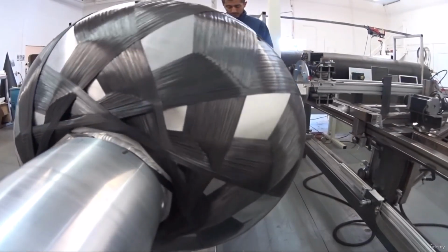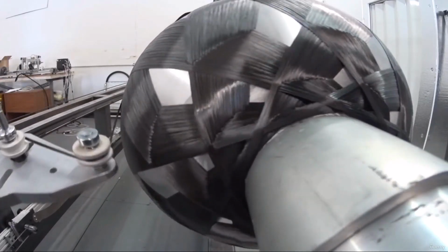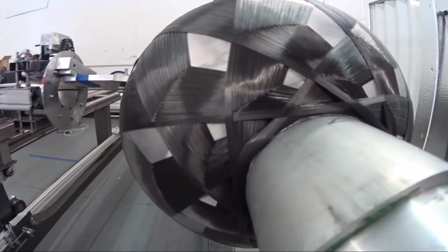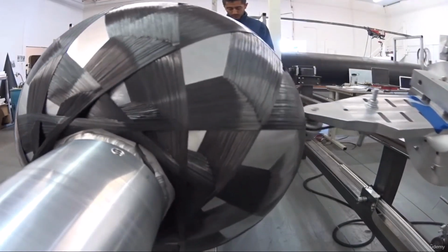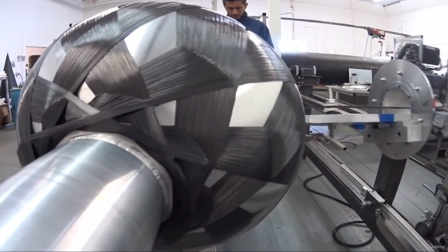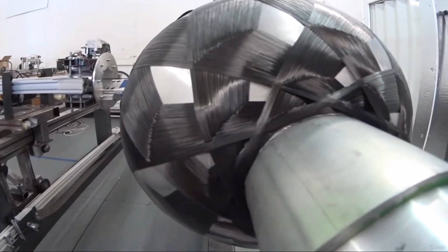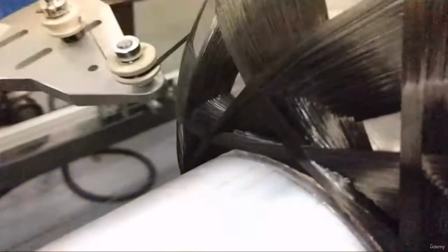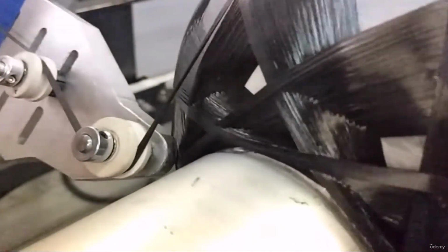Continuous fiber tows are fed through a fiber delivery system to a filament winding machine, where they are wound onto the mandrel in a predetermined repeating geometric pattern. Tow location is guided by a fiber delivery head, which is attached to the movable carriage on the filament winding machine. The relative angle of the tow to the mandrel axis is called the winding angle and can be tailored to provide the strength and stiffness in the desired direction.